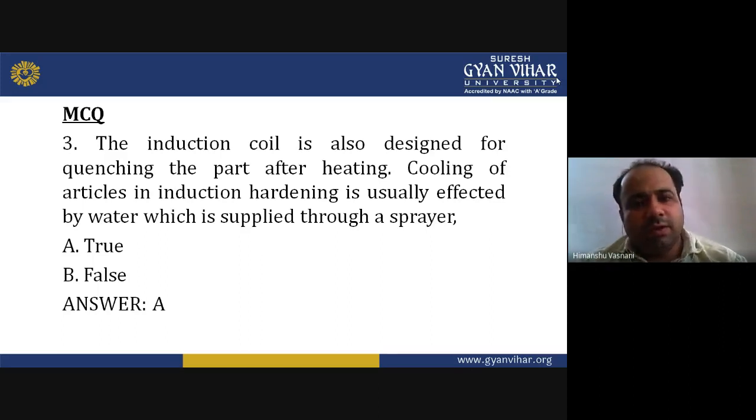So if you rethink the statement, the induction coil is designed for quenching the part after heating, this is true. Secondly, the cooling of articles in induction hardening is usually effected by water which is applied through a sprayer. So this is also true, and we have also seen this kind of arrangement in the diagram in the previous slides. So this statement holds true.